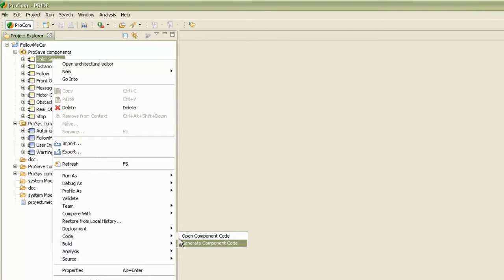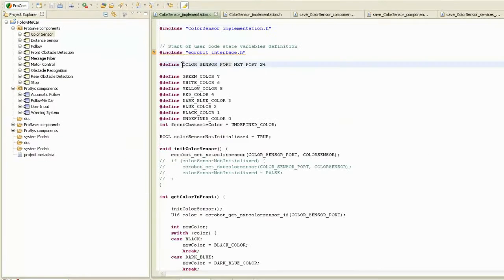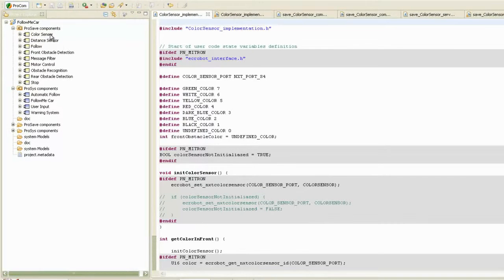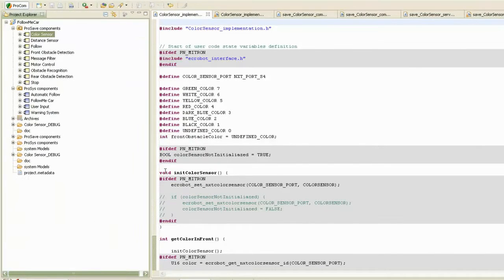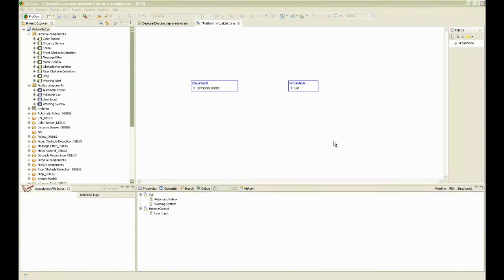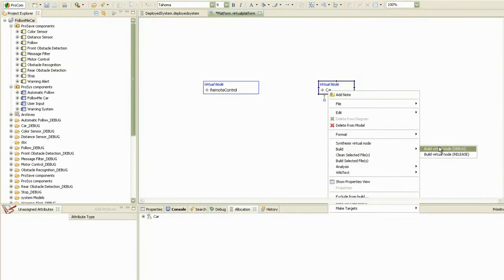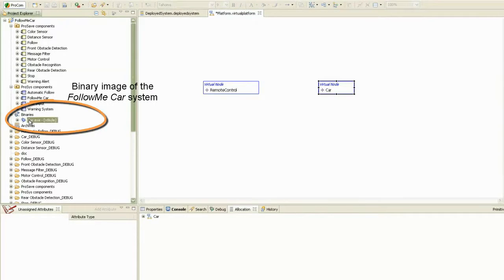We suppose that the implementation of basic function blocks is provided as C source code. The developer must fill missing code parts using those basic function blocks. The build process is incremental, passing through the production of binary libraries for each composition level. PRIDE allows to model allocation of components to the nodes of the physical platform. This allocation is used by the synthesis to produce the binary executable files for each node of the system.